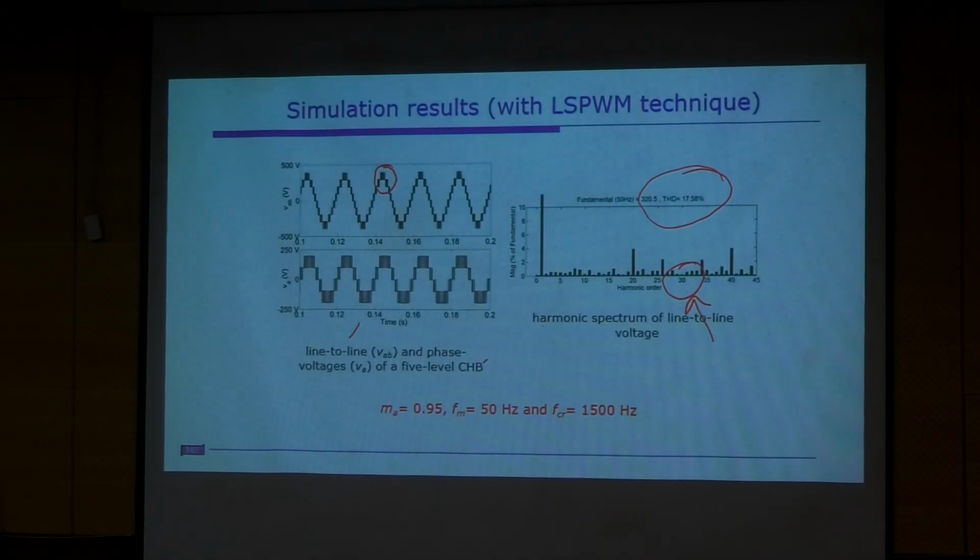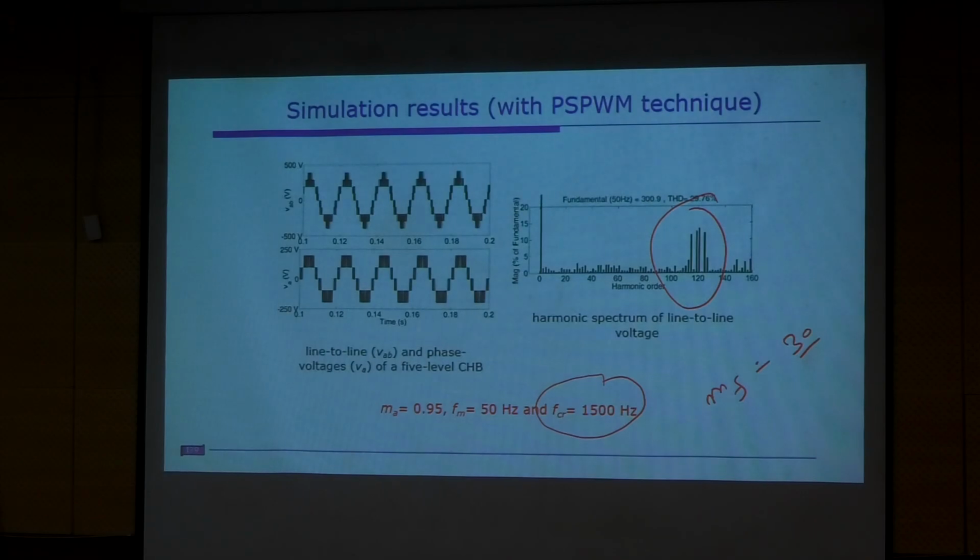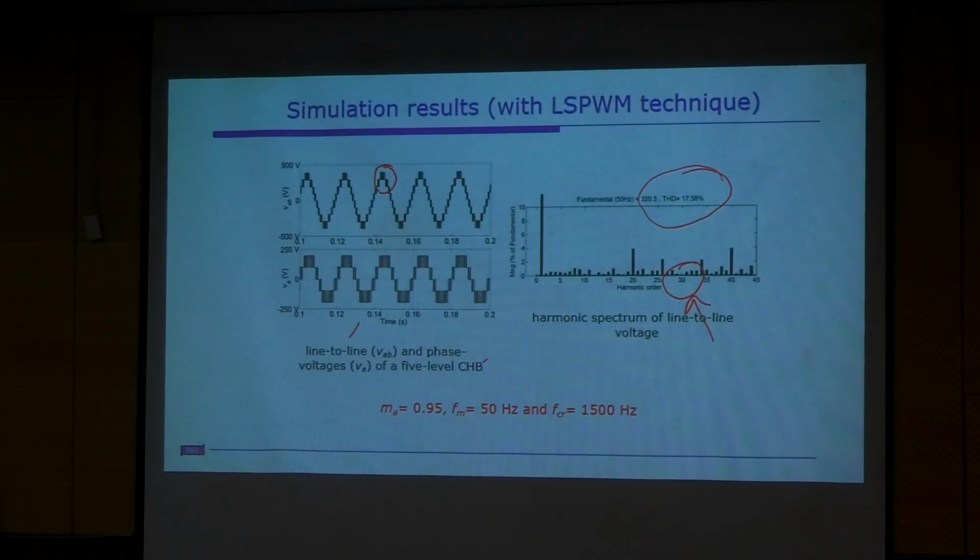Another thing is that you can also see the higher switching is operating, because we have thick lines. A lot of switching toggling is there, so we have higher frequency operation. Here it is lower frequency operation, because the inverter frequency itself is less. And the good thing is that the level shift PWM produces the better waveforms. In fact, the best waveform it will produce. We cannot beat this. Whatever output waveform is obtained by the level shift PWM is the benchmark. You cannot make it any better, so that gives you the clean output voltage.